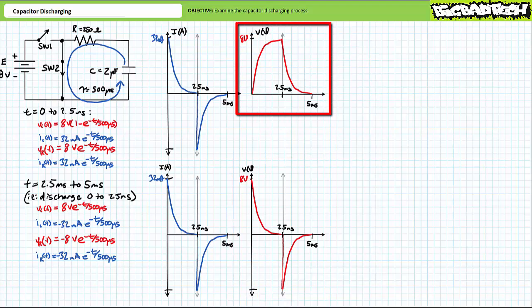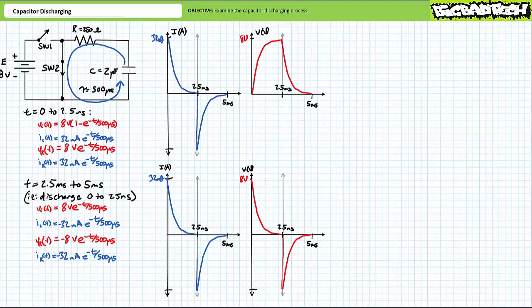Importantly, voltage across the capacitor, whether charging or discharging, never undergoes a disjointed instantaneous transition or a sudden reversal. That's the point. Capacitors resist sudden changes in voltage and are often employed in circuits that necessitate relatively steady or slowly changing voltage conditions. Additionally, you will on this occasion note the symmetry of the charge and discharge process. This is the consequence of the same magnitude resistor being employed for the charge and discharge path. It makes sense that the quantity of energy stored in the capacitor takes the same amount of time to accumulate and dissipate given equal transfer rates.